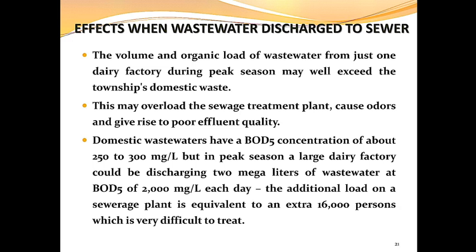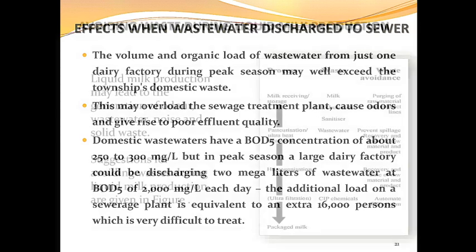Domestic wastewater normally has a BOD concentration of 250 to 300 mg per liter, while the dairy industry discharge may have 2000 mg per liter of BOD. That is the additional load on the sewage plant, and it may be very difficult to treat that much BOD in a domestic wastewater treatment plant. These are the effects of the discharge of dairy wastewater into the sewer.